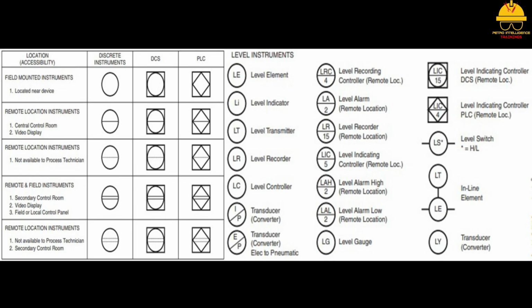Level indicators are very common on process drawings and are represented with an instrument symbol that looks like a circle with LI written on the inside. The symbol LE is used to describe a level element. An example of an LE is a displacer bulb. Level is typically controlled with a level control loop, LIC. In this system, each of the 5 elements of the control loop will be level related and labeled appropriately. It is also possible to have other level symbols like level recorders, LR, high-level alarms, HLA, and low-level alarms, LLA.